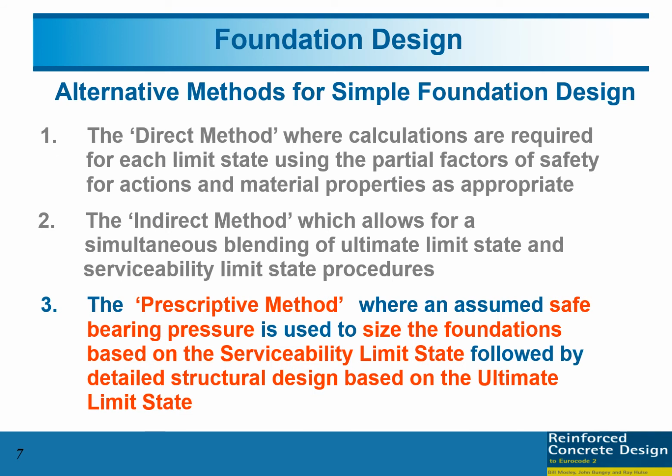Based on these 3 alternatives, we select the prescriptive method because this method has also been used previously during RC design 1 when you designed the pad footing. We need to determine the dimension of the foundation by using the serviceability limit state loading. And then when we design the reinforcement, we need to use the ultimate limit state, ULS.